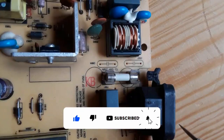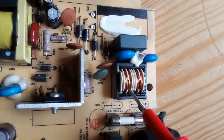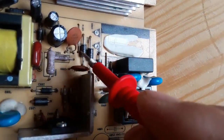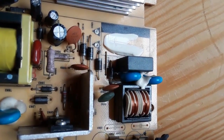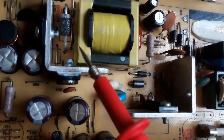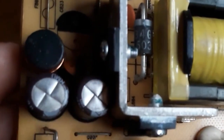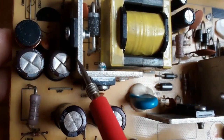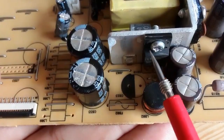Okay? So here, this is another flyback motherboard. This is the primary stage, where we have the fuse and electromagnetic interference. Those diodes are normal diodes, and over here we have Schottky diodes. As you can see, we have two Schottky diodes, one with two leads and the other mounted to the heatsink with three leads.